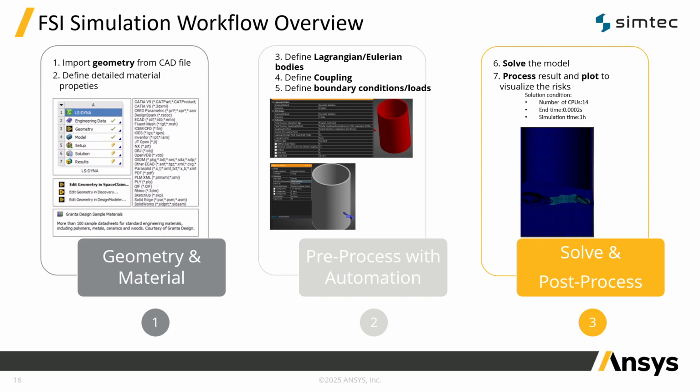After that, we must move to solving the model and monitoring. We must set the appropriate time step and stability controls, and we must always monitor convergence and physical plausibility. And the most important part is the post-processing.